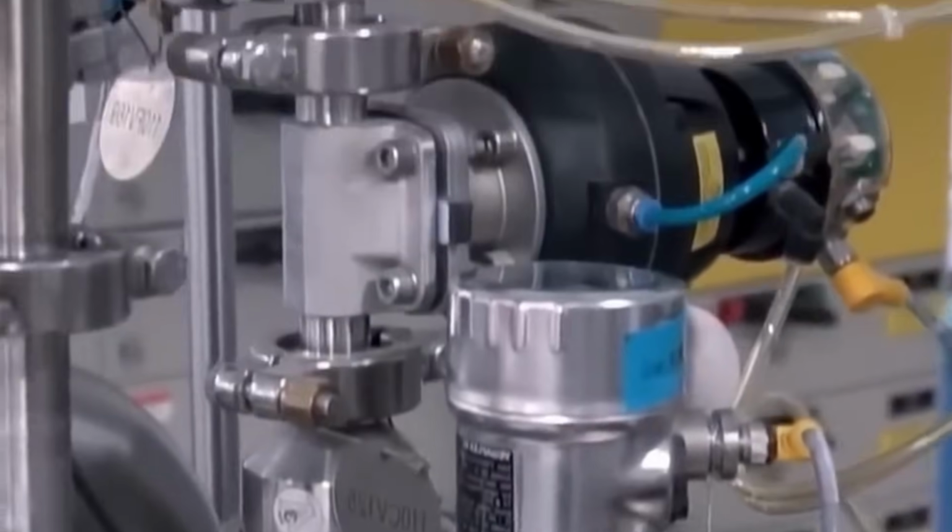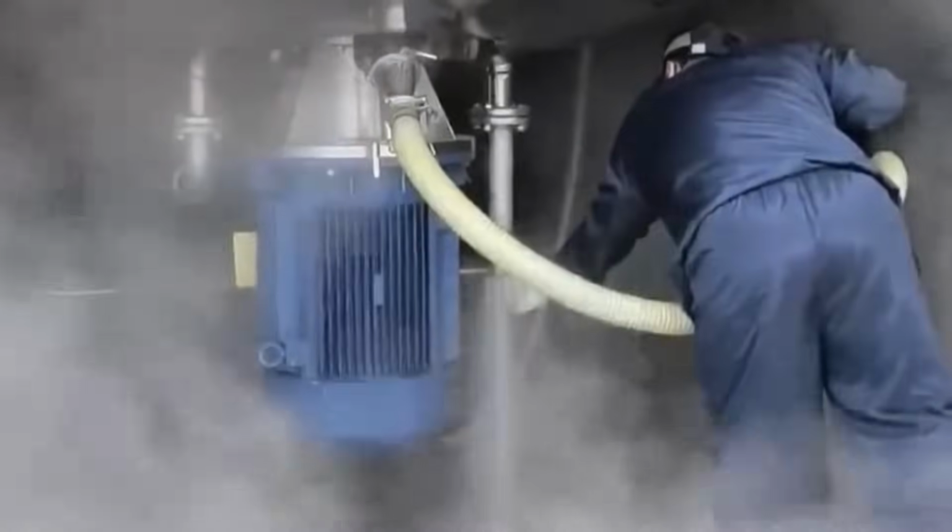Sensors verify the presence of a tube inside each carton. Incomplete units are automatically rejected through diverter arms. Cartons are grouped into shipping cases via a robotic case packer. Cases are assembled from flat blanks, filled, and sealed using hot glue or tape.